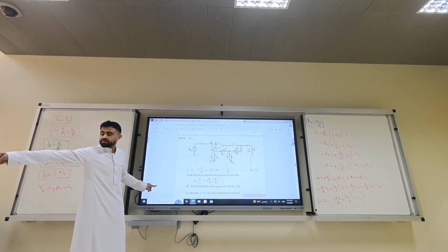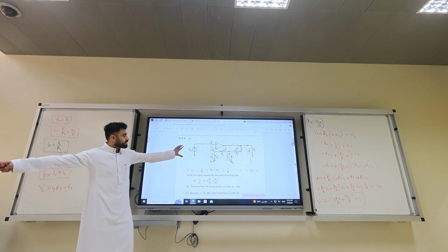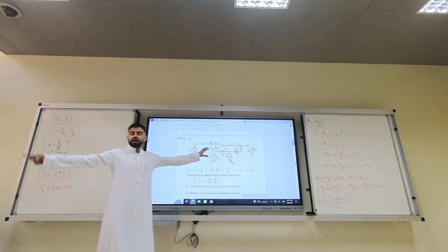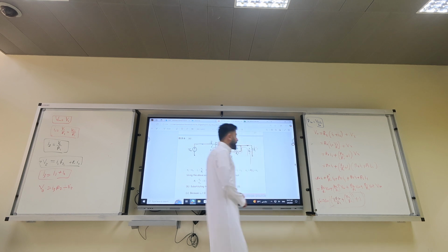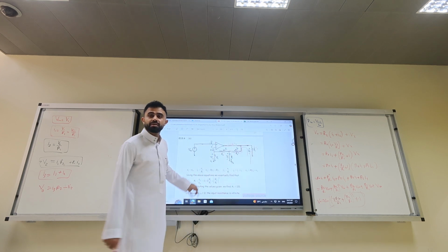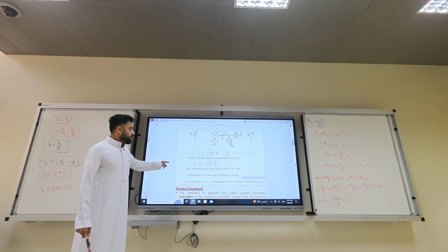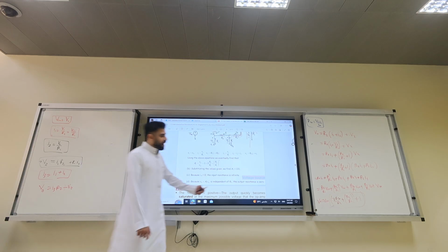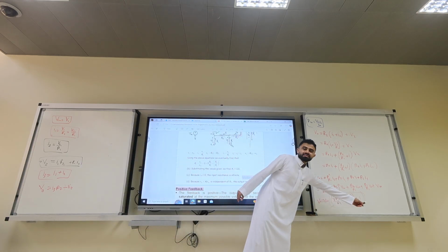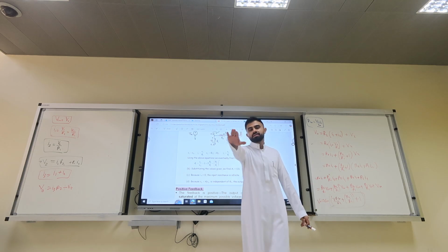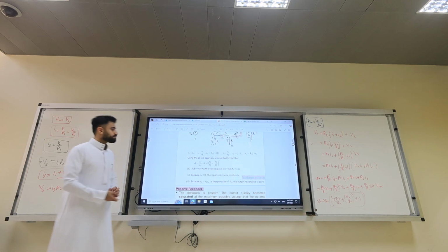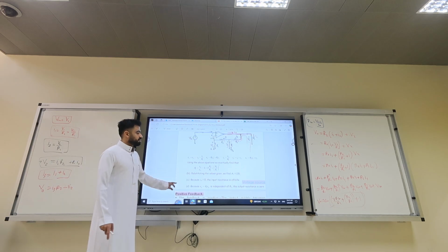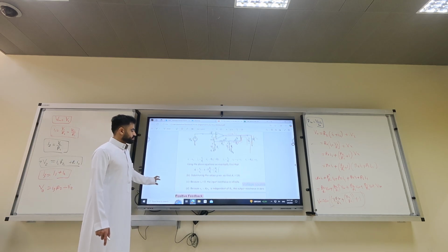What's the input impedance? Yeah, it's easy. Infinity. Why? Because it's V input over I input. What is the output impedance? Do we have RL here? No. So output impedance is zero. It means it drives whatever. Okay? So this acts like a voltage source.